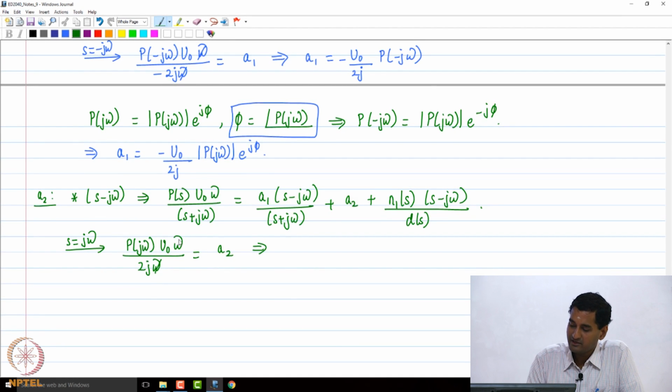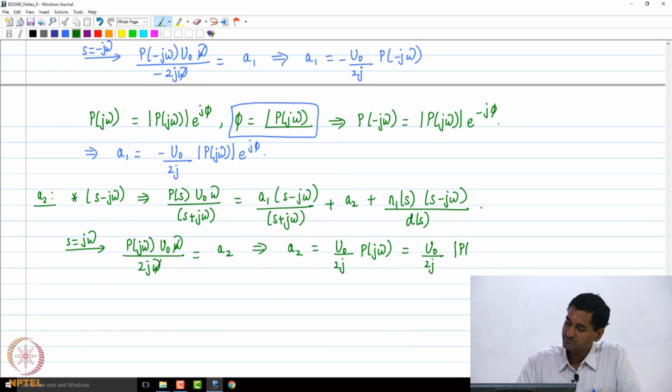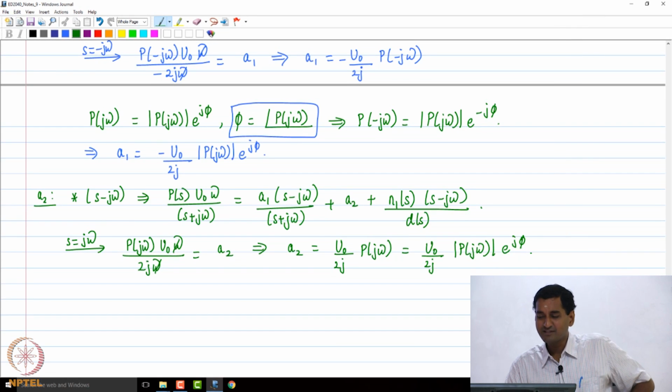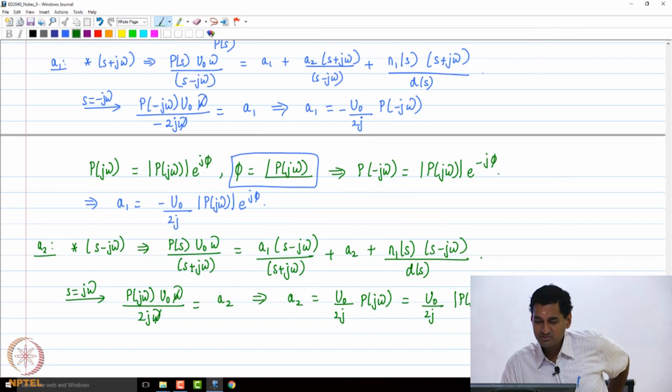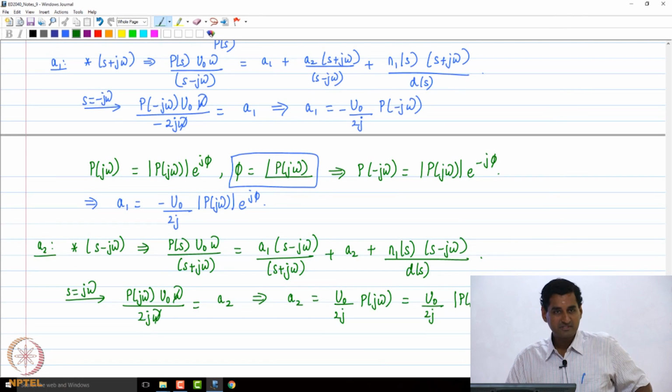Omega and omega will immediately cancel. So, A2 is going to be u naught by 2 j P of j omega, then I represent P of j omega as the magnitude of P of j omega e power j phi. So, we are almost done, just a few more steps.